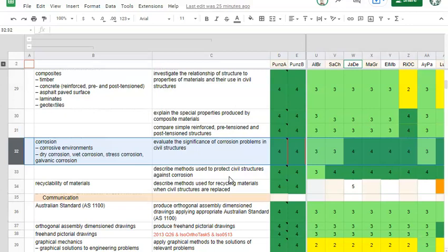Now, they will give you a galvanic series. If you don't know what a galvanic series is, you need to ask a teacher, right? But when they provide you with a galvanic series, they'll usually put gold on there somewhere, and they'll usually put zinc on somewhere. So zinc is the anode end. There are always arguments about platinum and magnesium and other ones that could be on this series. But if you can find gold, that's the cathode end, because they have to give you the series. They don't have to label the series.